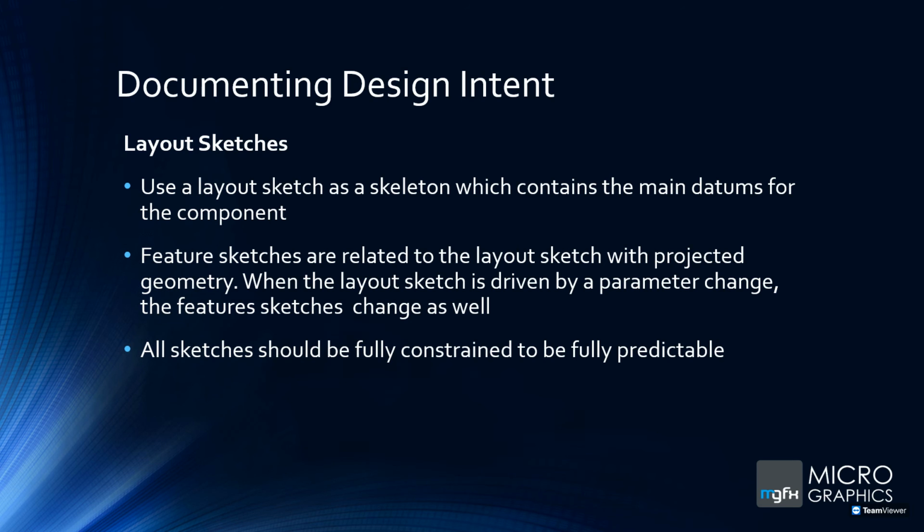We've got work planes, which we can put onto a layout sketch. So you've got a layout sketch, and your work planes are connected to that sketch, and then you put additional sketches on those work plane datums and run additional features on them. This way we can control things a little better, because if you start putting sketches on existing feature faces and something goes wrong with that feature face, it's going to destroy your sketch as well. So there's more involved when you put features on features or sketches on features, which are those relationships we spoke about earlier.